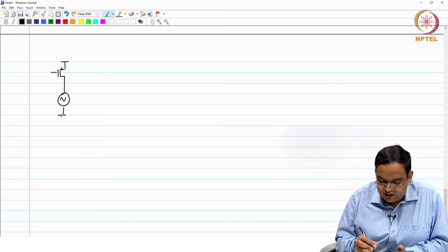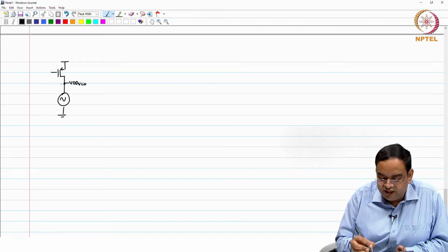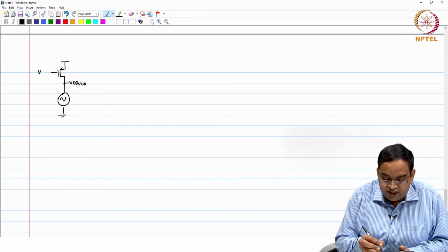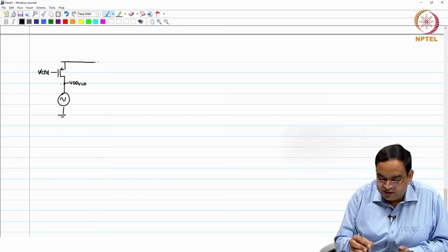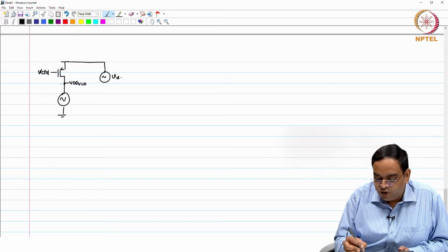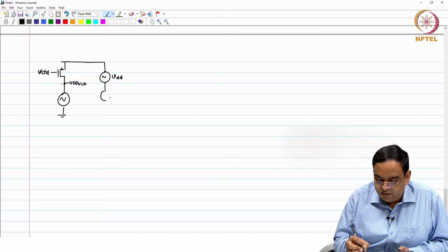Okay, this is the oscillator, and I have this. I am just calling this node VDD VCO. There is no specific voltage source connected. Okay, don't get mistaken by that. So, this is V control, and I have the supply voltage. So, let us say I am modeling the supply voltage with some noise small VDD and whatever capital VDD you need.